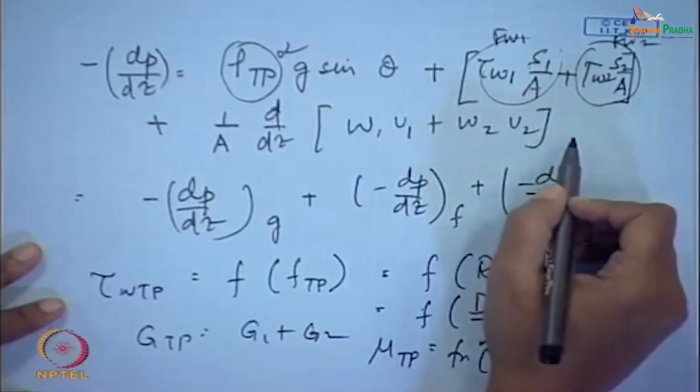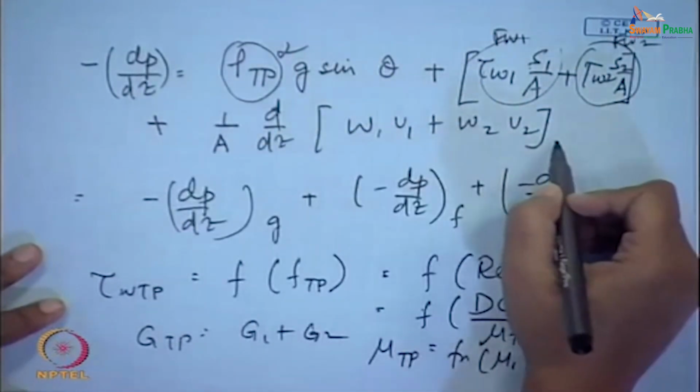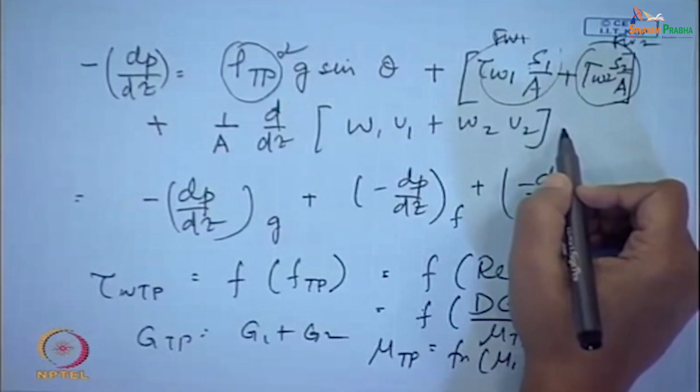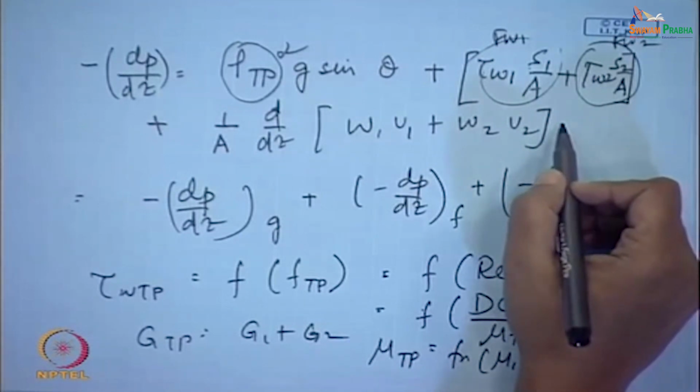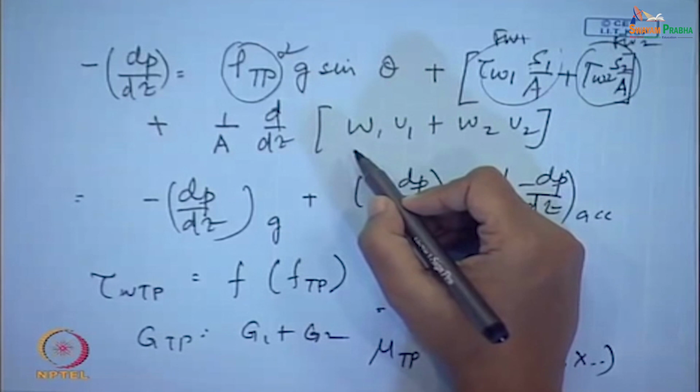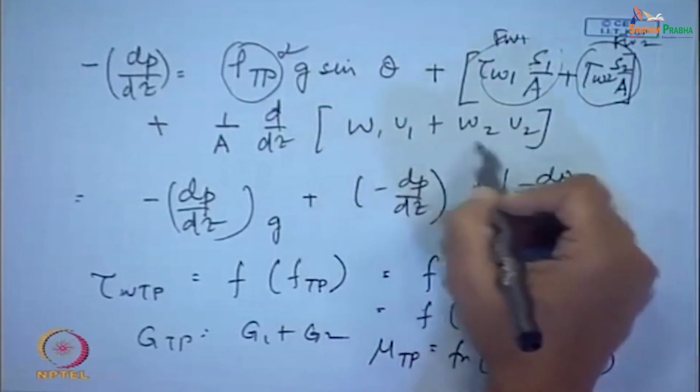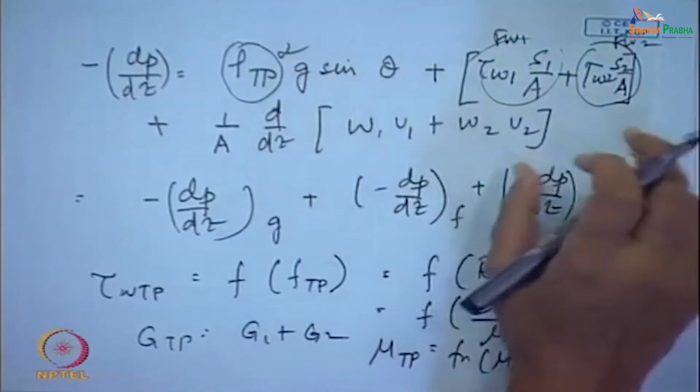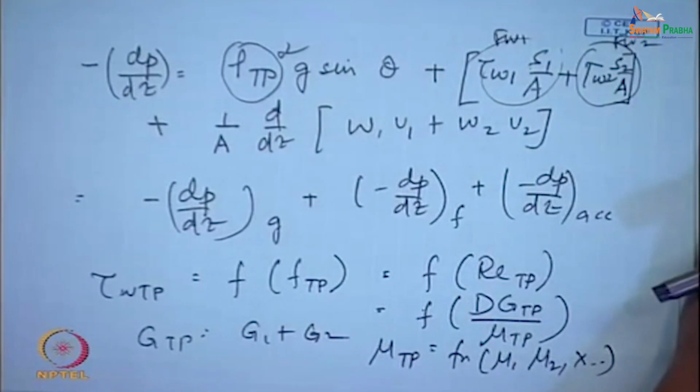Okay. So, first what we will do, we will first try to derive this equation in a form which will enable us to find out the pressure drop from known input parameters. For that we will be dealing with the acceleration pressure gradient just as we had done for the homogeneous flow theory. Now, moment you know, whenever we try to expand this U1, U2, normally what happens, we get some terms containing dP dz, is not it? Why? Because V1, V2 etc. they vary with pressure. Okay. So, when they are brought on the left hand side, we find that the final pressure drop equation, it has a denominator. From there we go to derive the condition of choking.